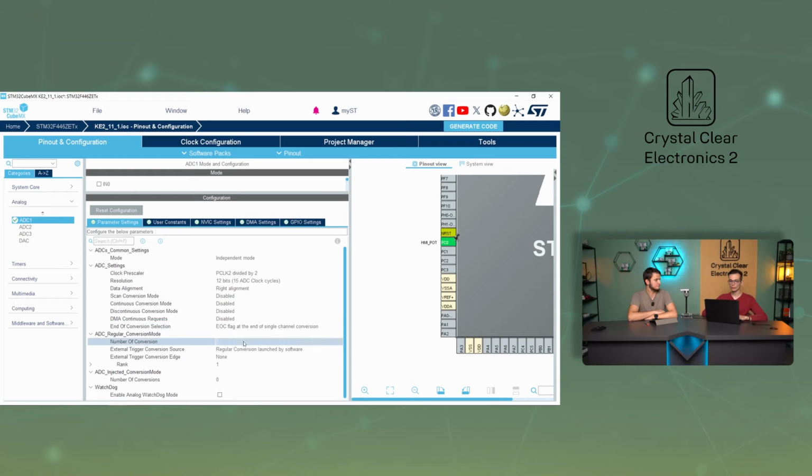You can set the conversion process to be triggered by an external trigger event or by a predefined method initiated by software. For example, an external interrupt can be generated by the microcontroller's hardware timers to start a conversion at an expiry time, saving some operations compared to if the same had been done with a software timer. In case of a software-triggered conversion, the process will be started by a function call. How to do this will be explained a bit later.